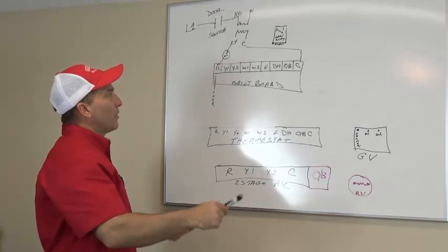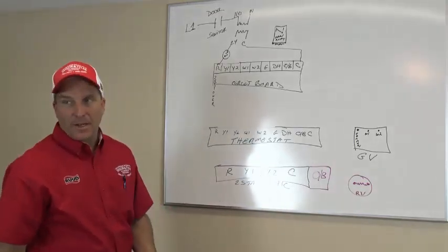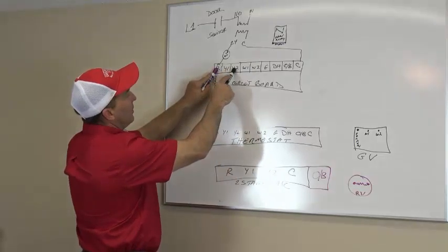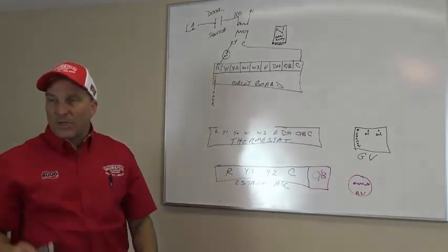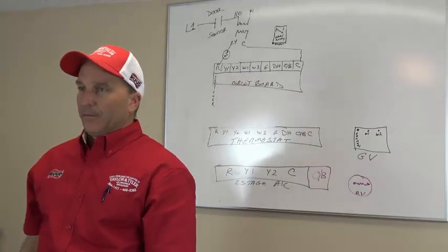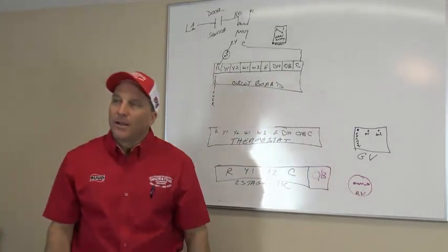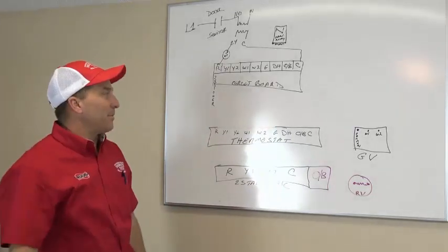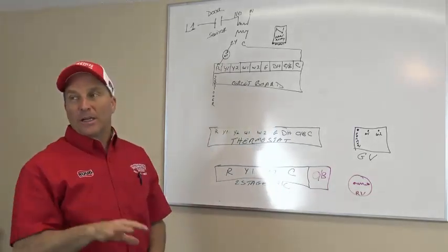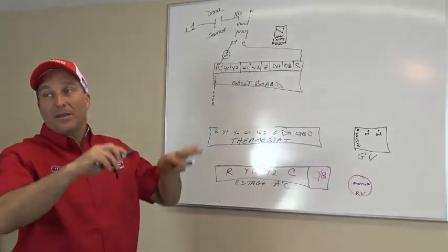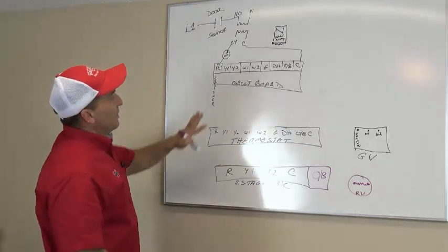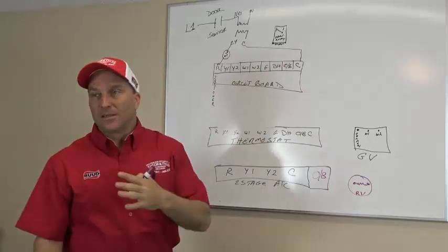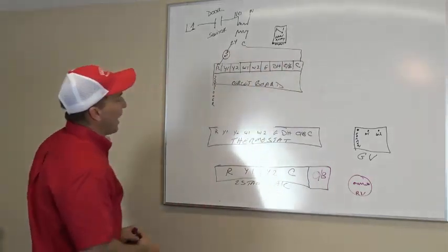Okay, let's go back over this again then. Between here and here, what am I reading? I'm reading 24 volts. That doesn't make sense. Oh, it's traveling back around. Let's go and complete our circuits here. We haven't completed our circuits yet. If nothing is attached here, we read 24 between here and here, but something is attached. So how is it attached?